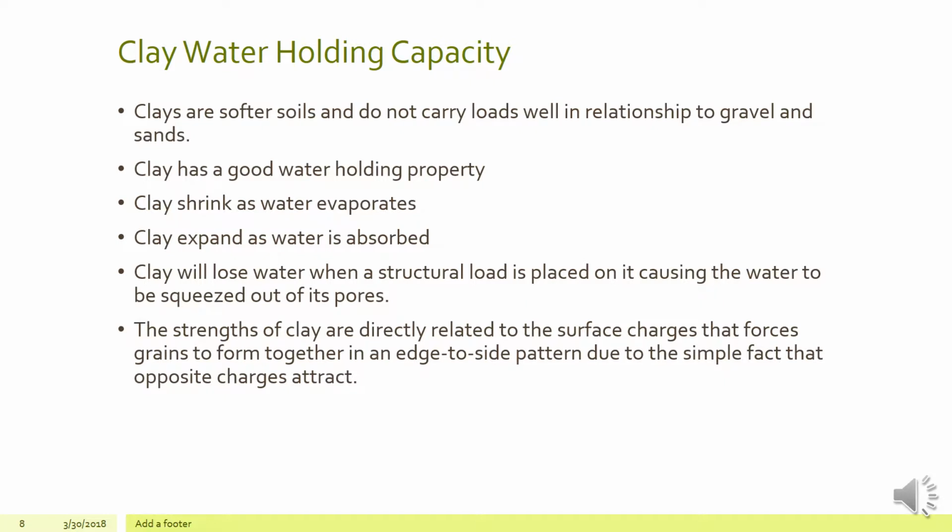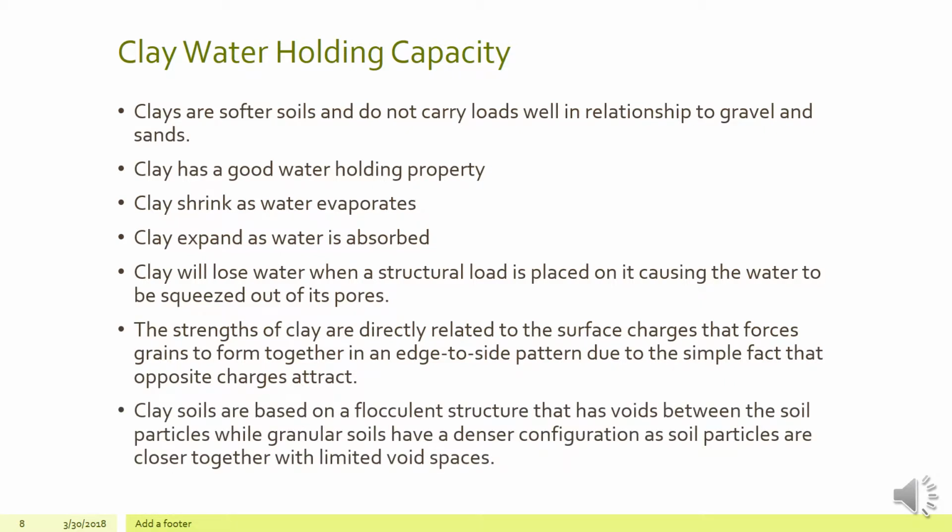The strength of clay is directly related to the surface charges that force grains to form together in an edge to side pattern, due to the simple fact that opposite charges attract. Clay soils are based on a flocculent structure that has voids between the soil particles, while granular soils have a denser configuration as soil particles are closer together with limited void spaces.